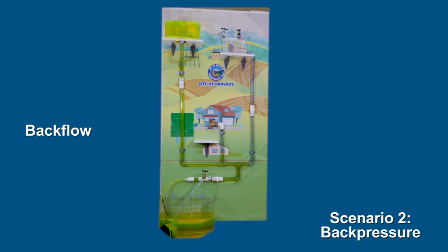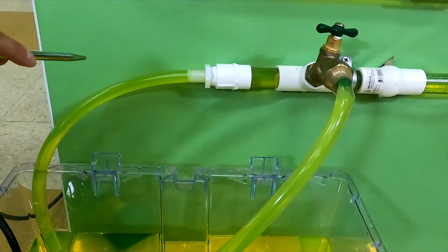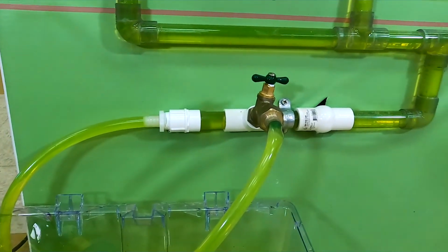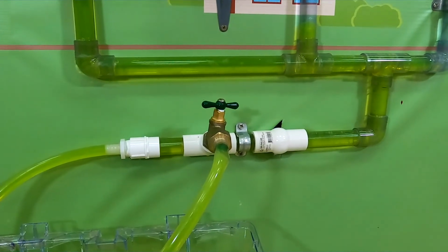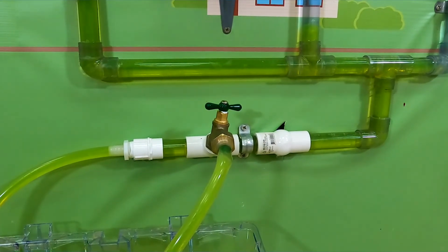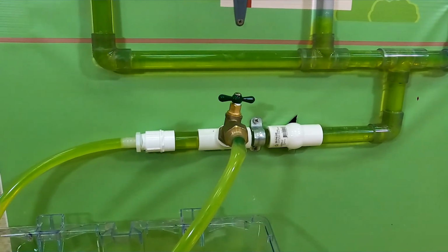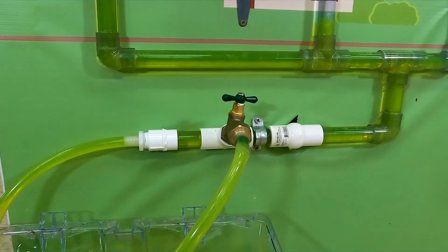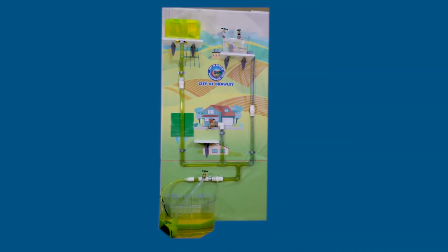Water distribution operators are called again, and while carrying out their investigation, they visit the homeowners who have access to IID canal water. They find one homeowner that does not have a backflow device. They also find a cross connection between the drinking water and the IID water. The inspector requires the homeowner to disconnect the cross connection and install a storage system with an air gap, or place a reduced pressure backflow prevention device at the home's point of connection to city water supply.